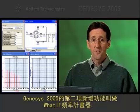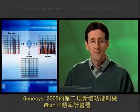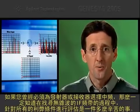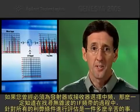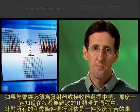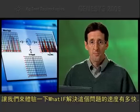The second new feature available in Genesys 2005 is called the What-IF Frequency Planner. If you've ever had to select an intermediate frequency for a transmitter or receiver, you know how difficult it is to examine all the trade-offs in finding an IF band that is spur-free. Let's look at how quickly What-IF can solve this problem.